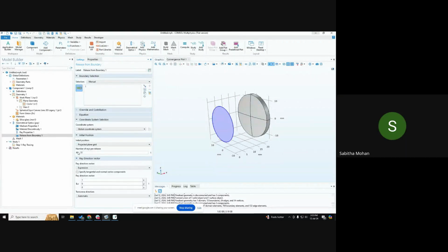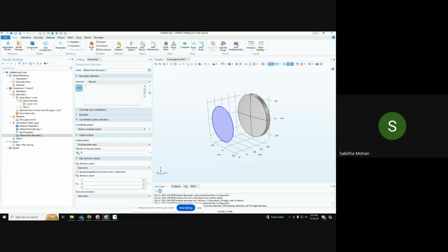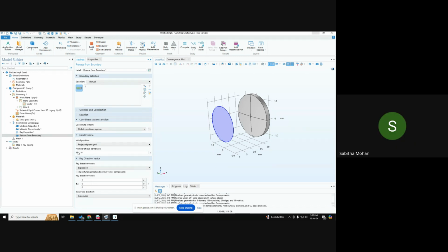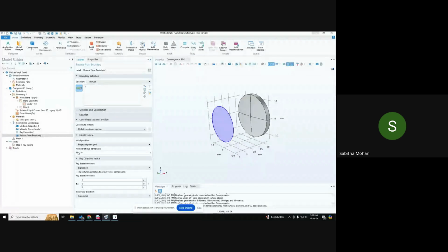Sir, how will we be able to define the other properties of the light source, such as coherence? Coherence cannot be modeled with ray optics. For coherence and other properties like interference, you have to model the complete wave optics part. Interference is very difficult to do with ray optics. It's next to impossible to do it with ray optics.